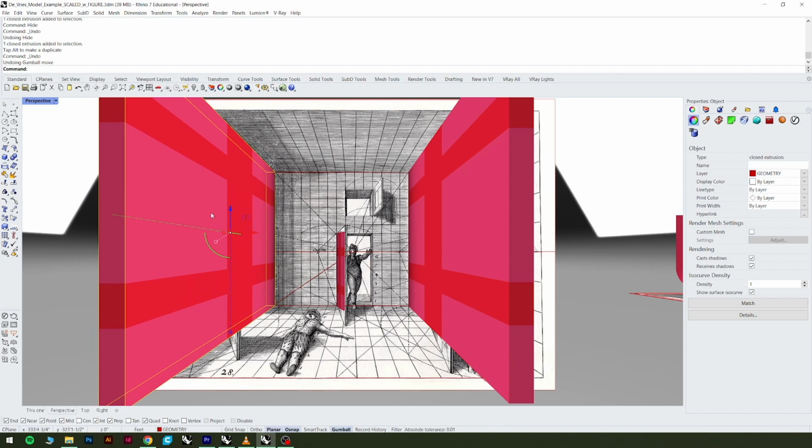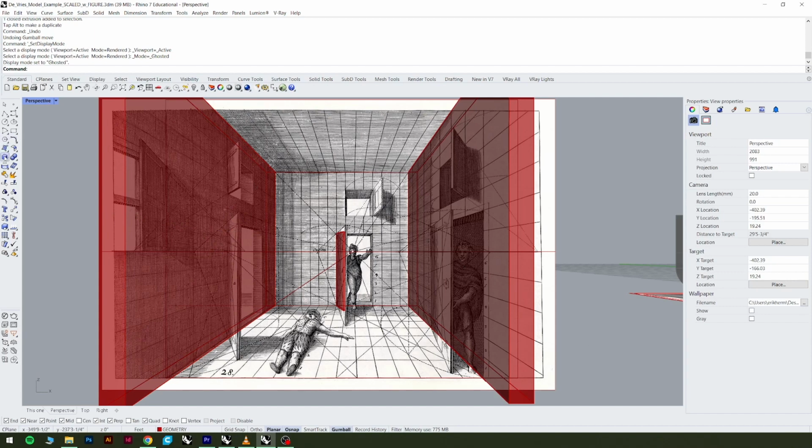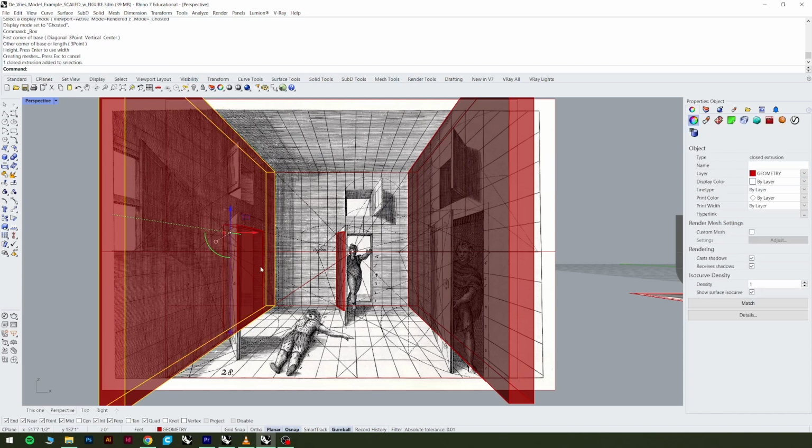The challenge is then, okay, now I need to make those windows and all these other things. So then you might want to go into a ghosted viewport. And if you are modeling these things, the easy way to do it would be to draw in 3D on top of what you've already built. So I've already built that wall. I'm just going to try to draw this door opening and see how well we can get that lined up just by staring at it in perspective.